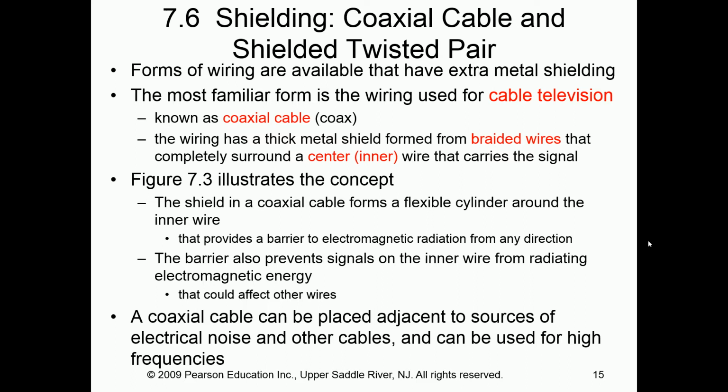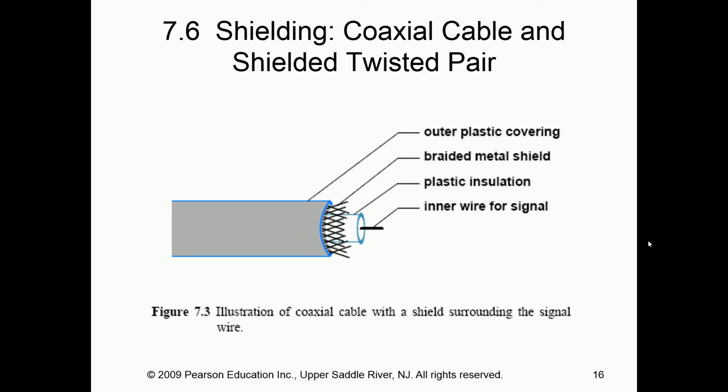What we could also do is use coax. One of the nice things about coax is it might not be as great as shielded twisted pair, but it has additional layers of protection. We have a center core, a copper core. Then we have some form of plastic coating or insulation or cladding. Then we have a metal mesh shield.